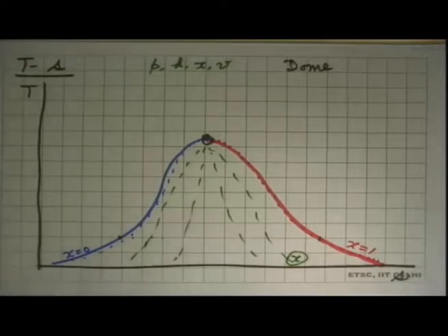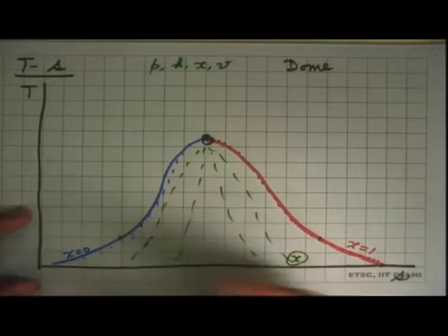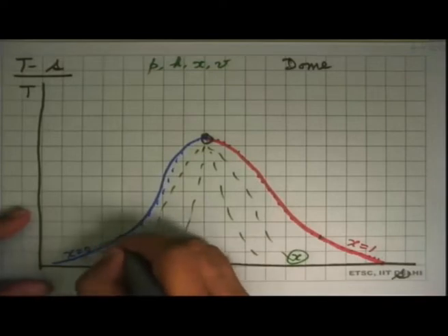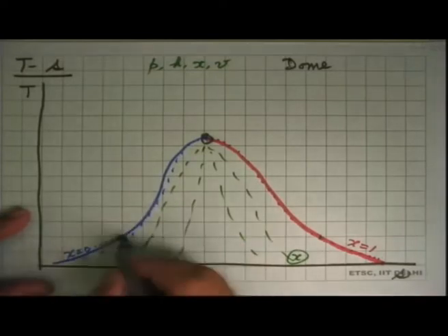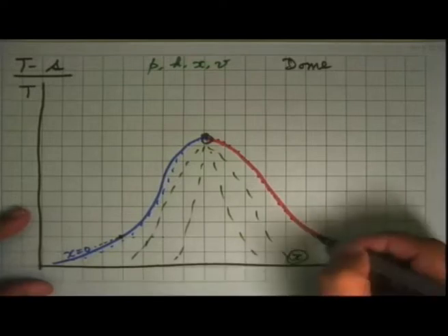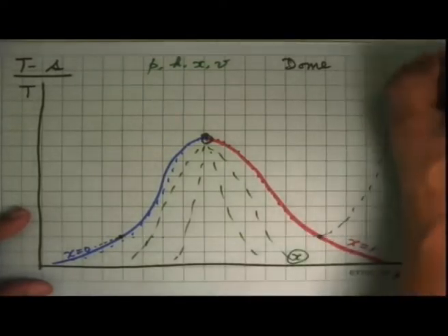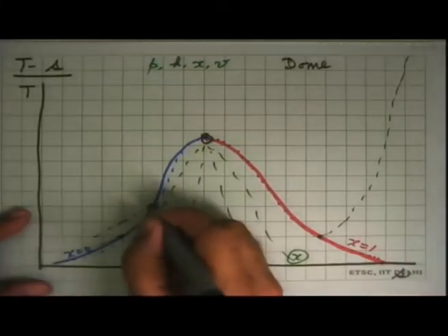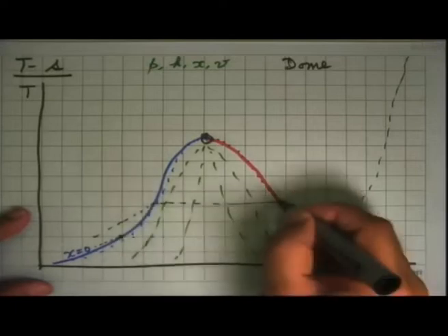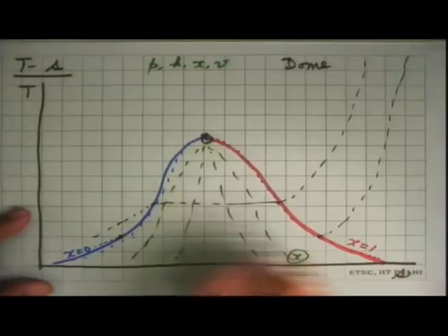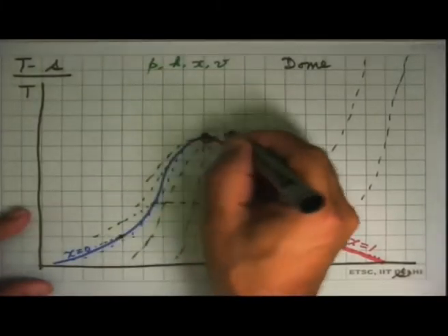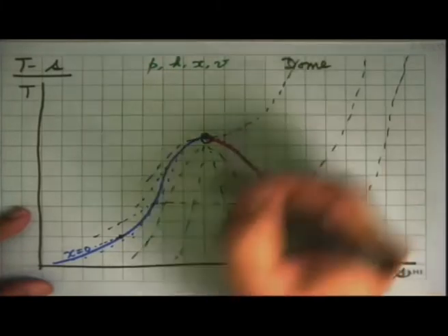Now we ask for constant pressure lines. What happens is we do the same, that TV type of a thing here. It starts from here and very quickly, say, comes to a saturated liquid state. Then the pressure is constant, and then from here the constant pressure line begins to go up. Then we come to another point there, and then again it starts to go up. At even higher pressures we come there, and finally at the critical pressure we get this critical isobar.